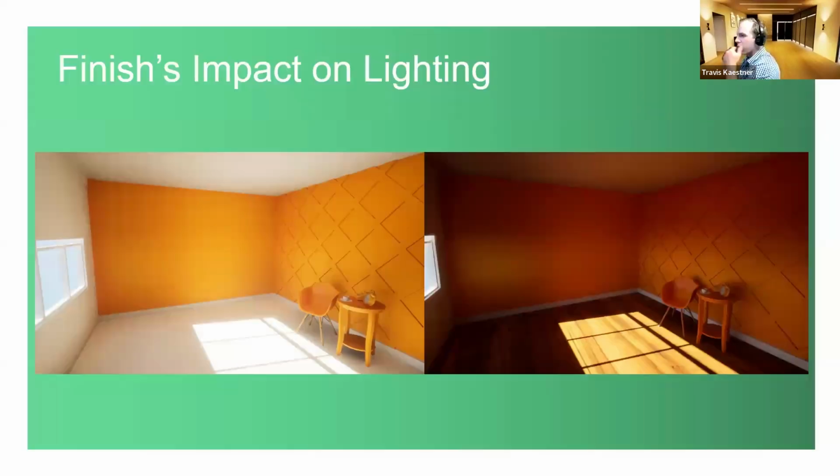Think of that. I remember I did just a warehouse, a typical layout, and it showed 40 foot-candles, and everything was supposed to be white. And then I went and walked it and it was like 10. And I was like, what happened? And they painted everything gray, and that ate up a lot of the light. So it does have a fairly large impact.